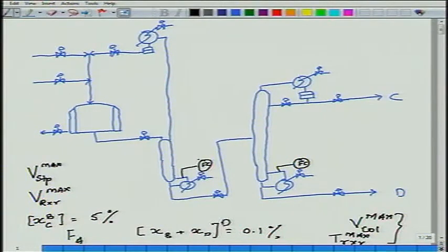okay. Reactor temperature and reactor volume are actually CVs, controlled variables. They are not direct manipulated variables, they have to be controlled, right. What is the tightest way of controlling reactor temperature which becomes active later on? Let us back off, because these constraints become active later on. Let us talk about product purity control, because product purity has to be tightly controlled, this chap. Therefore X B and X D will have to be tightly controlled, right.